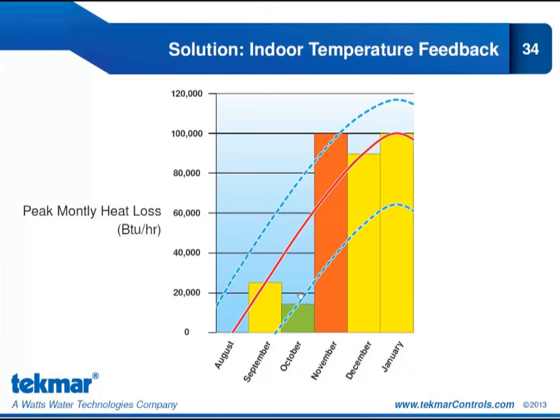If I'm operating strictly based on my outdoor reset curve, my supply water temperatures are going to be much higher than they need to be. What indoor temperature feedback does is it will decrease the supply temperatures by shifting the heat curve down based on the input from the zones, so that my reset curve is shifted down so my heat supply more readily matches the heat loss.